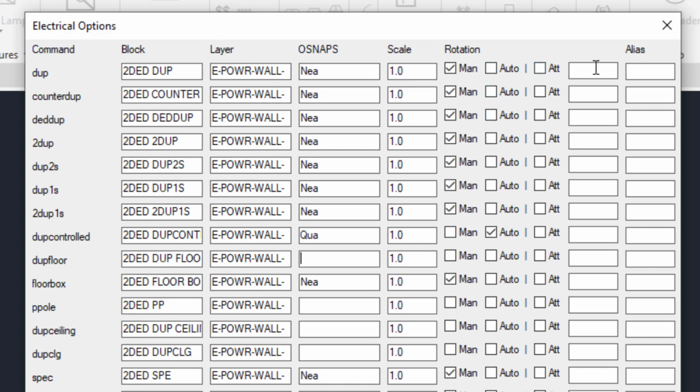And then after this is rotation, also rotation of attributes. So if you click the attribute rotation for a block, and that's all you do, it will have a preference to be down or to the right, never left or up, and still aligned with the block. If you click the attribute definition rotation here and type in a value, which normally would be 0, it will force the attribute to level, horizontal. An example of that, if you watch this whole video, is all the way back to the numbered note flag that I had. It'll do that.